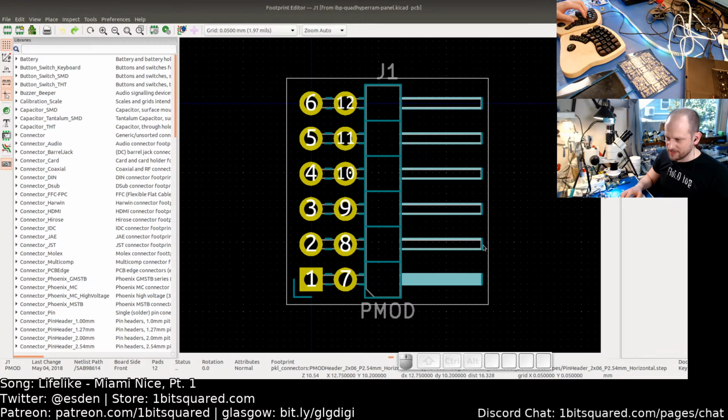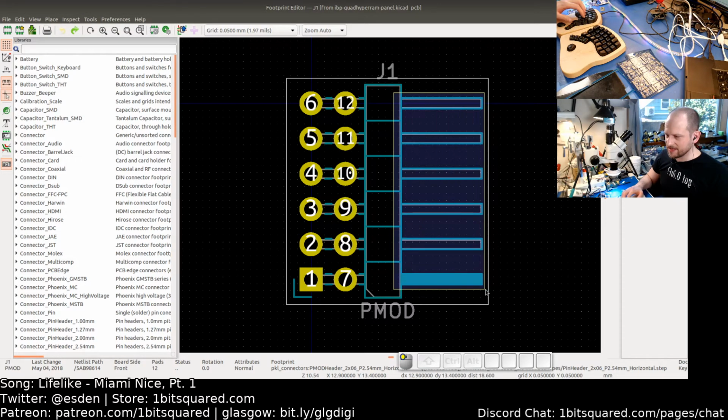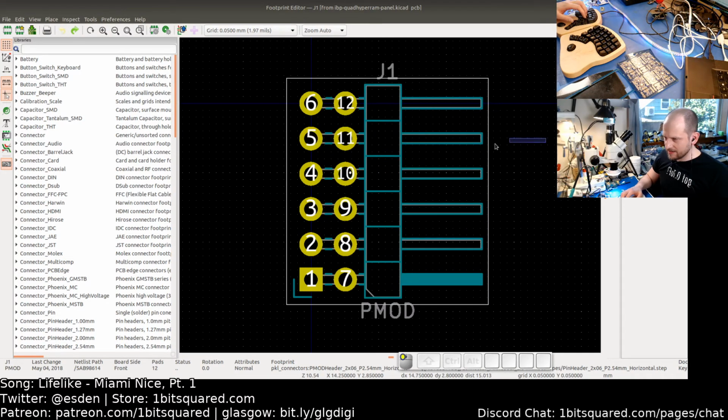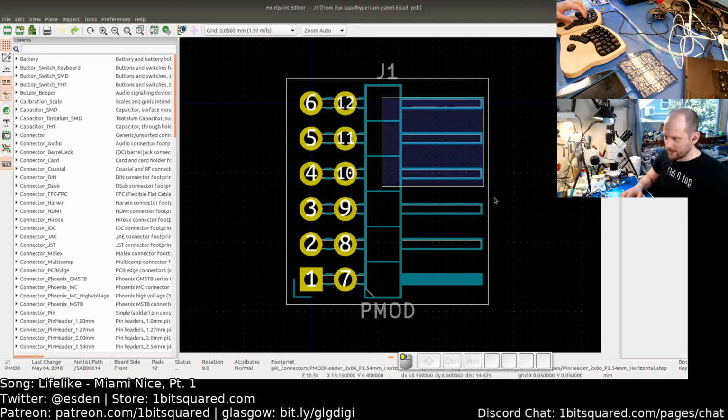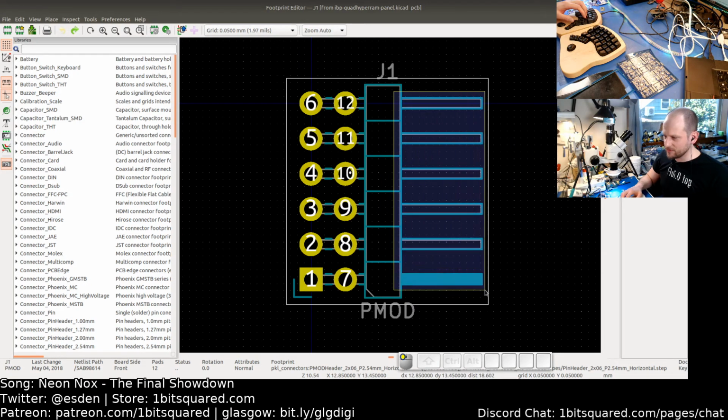So for example, it didn't select the tips here because I went from right to left and it was only selecting the lines here. It's a nice trick to know, and you see the difference between yellow outline select and blue outline select. From right to left is blue, and from left to right is yellow. So that's a new useful tool.